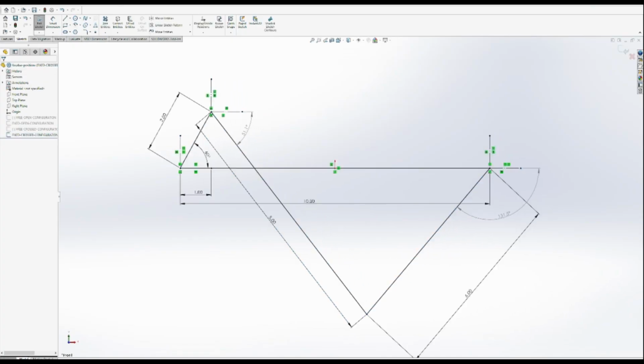So now let's see if we're getting the same results as our parent equations predict. Our parent equations predict that we should be getting a theta 3 of negative 51.1 degrees, which we are. When we're going clockwise, our theta is negative, and when we're going counterclockwise, our theta is positive. So since we're going clockwise relative to our local coordinate axes, we're going clockwise 51.1 degrees. That is negative 51.1 degrees. So our equations have predicted that correctly.